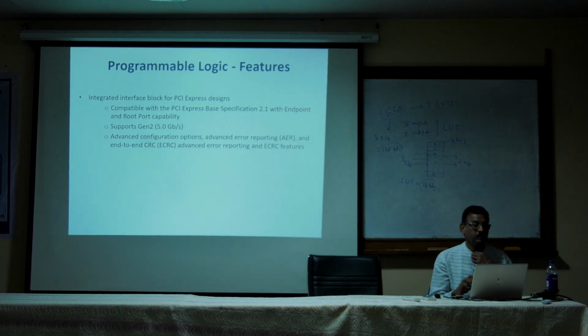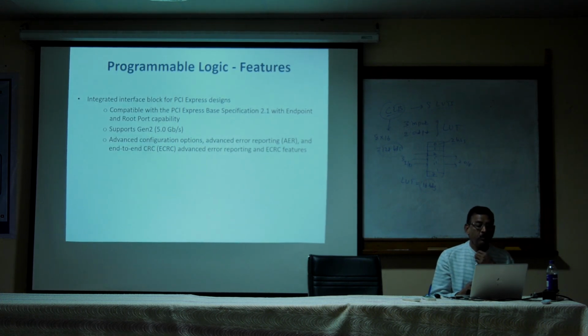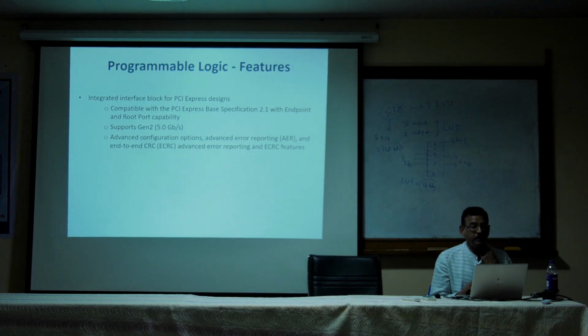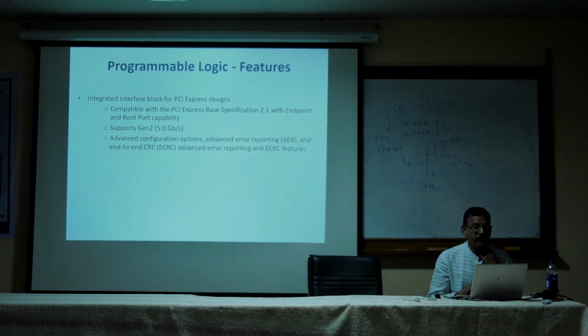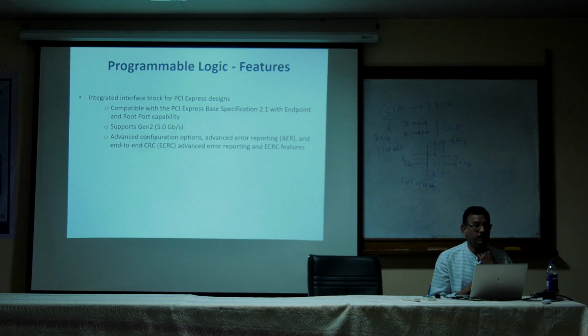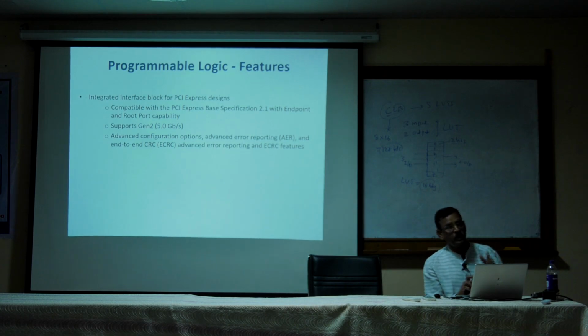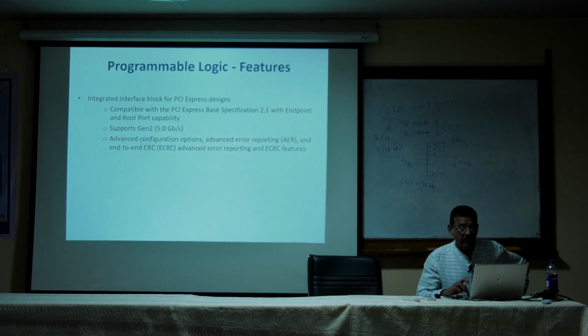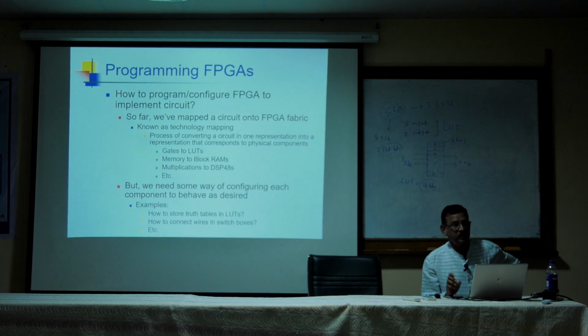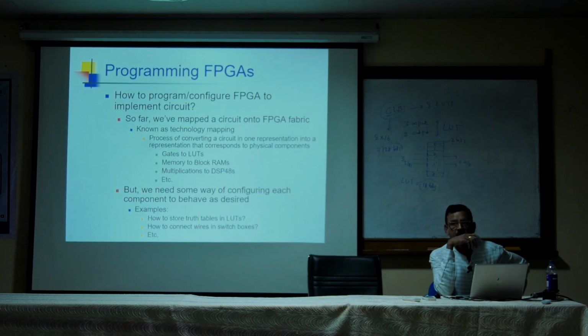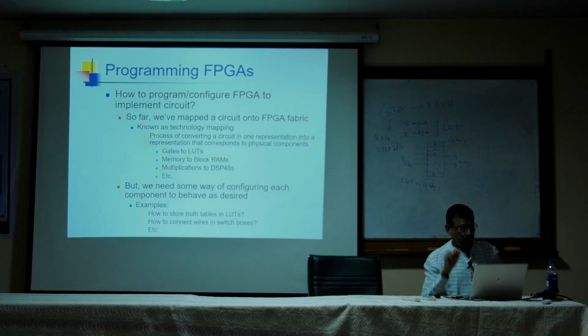It is compatible with PCI Express base specifications and supports generation 2, 5 gigabits per second. Advanced configuration options, advanced error reporting and end-to-end CRC, advanced error reporting and eCRC features. These are important features for this FPGA fabric, the Zynq 7000 FPGA.